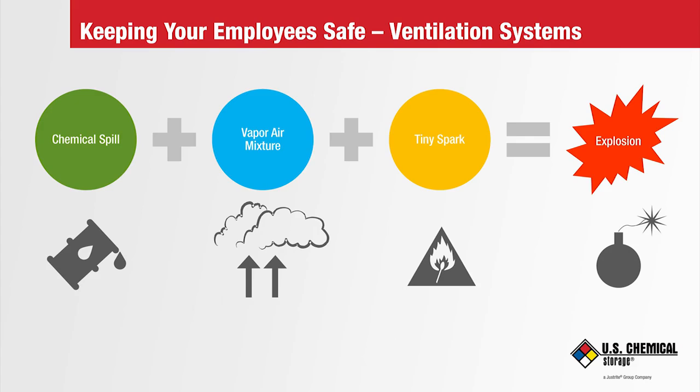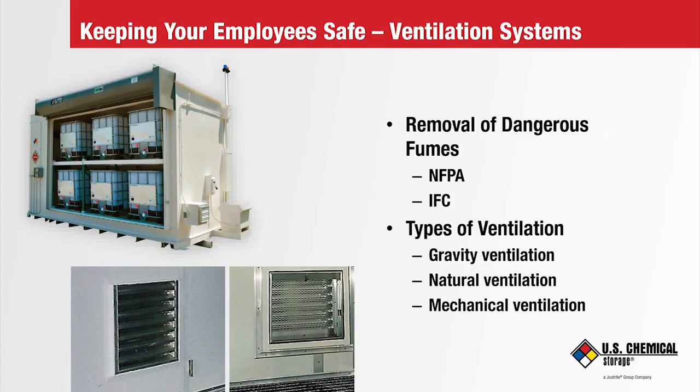NFPA 30 Flammable Combustible Liquids Code, paragraph A-4-6 says simply, quote, ventilation requirements include mechanical ventilation where dispensing operations are expected, unquote. We'll talk more about the different types of ventilation systems on the very next slide. There are three types of ventilation systems.